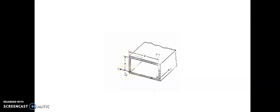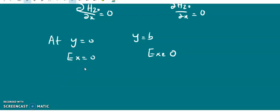So at y equal to 0, meaning the xz plane, the tangential component is Ex, and at y equal to b also, it is a plane parallel to the xz plane. So the tangential component is again Ex. So Ex is equal to 0 at y equal to 0 and y equal to b. Ex0 is also 0, because Ex is Ex0 e to the power minus gamma z, and e to the power minus gamma z cannot be 0.